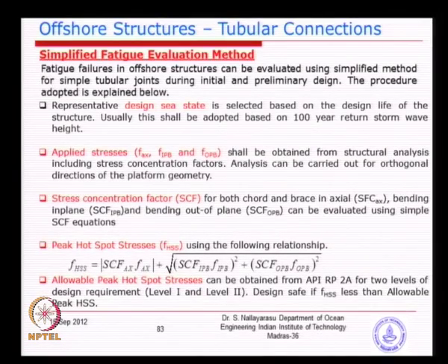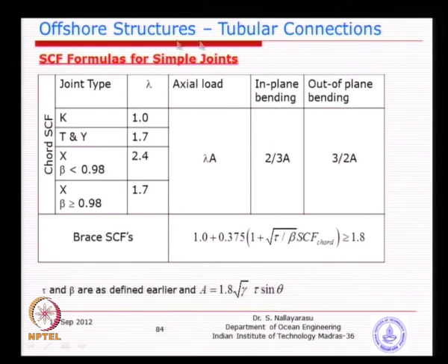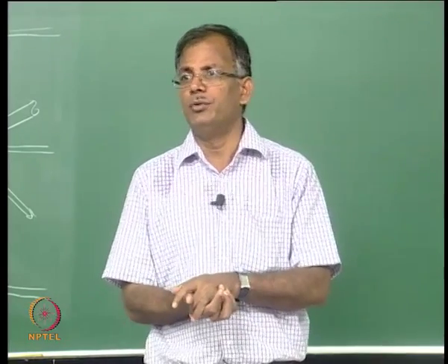In association with this, they also have recommended a stress concentration formula, which is very simple. You will see this is one page covering almost all joints and basically all possible load types. So, you have TKY and X joints, as well as axial load, in plane and out of plane bending. All cases are given there, and this also is very much coming from very early works like 1970s preliminary works on the stress concentration, and that is why the formulas look so simple and can be used very quickly.